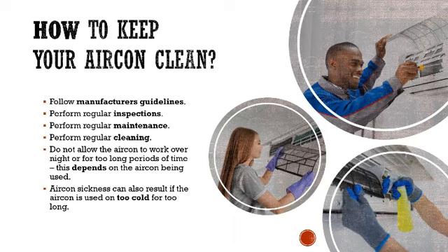Open up the actual aircon from the front, obviously making sure you disconnect it first. And then you will notice that there's maybe 1 or 2 little screws that only hold in the filter section. So we're not touching anything out on the compressor on the outside. We're not taking off the AC unit on the inside. We're just opening up the flap that is very easy to open. There's no huge maintenance issues here.